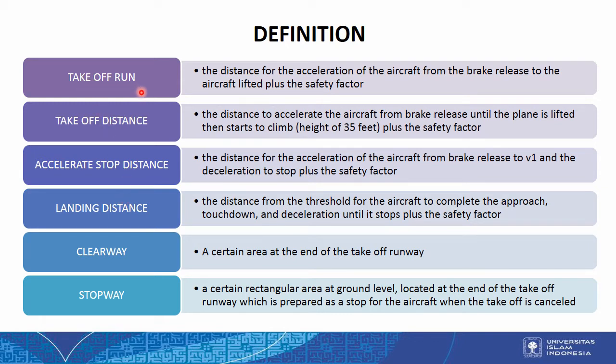So the takeoff run is the distance for the acceleration of the aircraft from the brake release to the aircraft lift, plus the safety factor. The takeoff distance is the distance to accelerate the aircraft from brake release until the plane is lifted and starts to climb to the height of 35 feet, plus the safety factor.